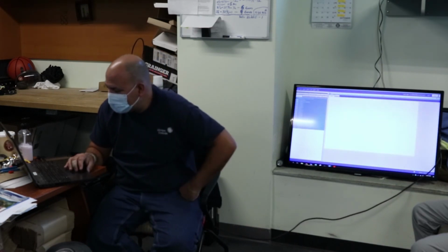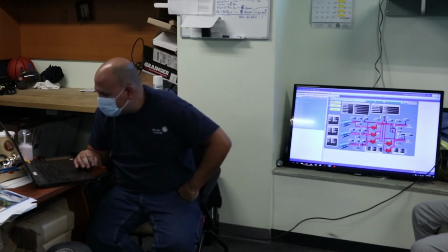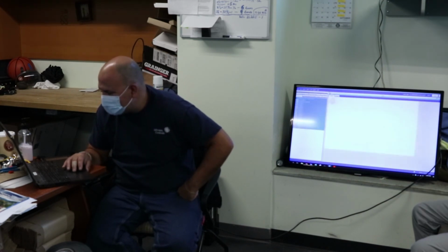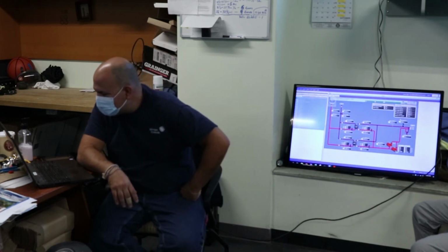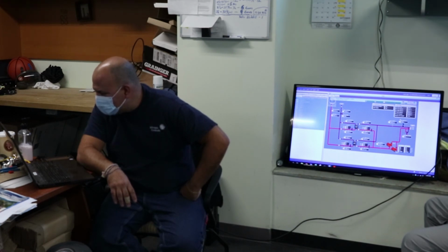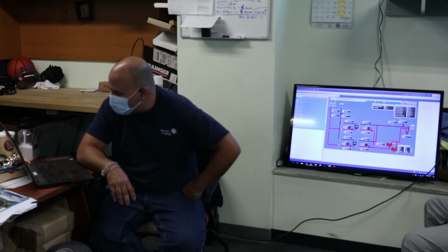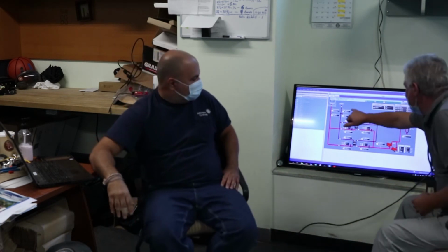If it isn't, Aramark's not going to approve this. This is. Yeah, it's resetting, based on 180 on the high, 140 on the low. So at 30 degrees outside air it will be 180, and at 65 degrees it will be 140. It's going to overheat the whole building. We brought this one all the way down to 110. They have a limit on the VAVs. They won't let the discharge air go above 92 degrees.